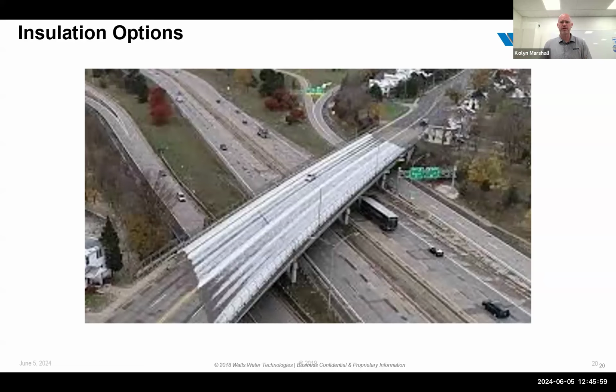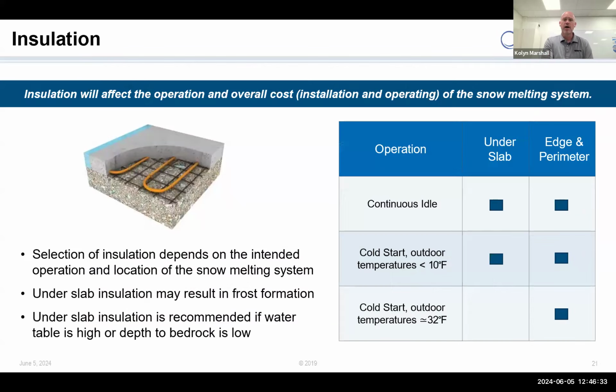When you decouple the snowmelt area from the earth, those fall days, those shoulder days where you actually end up with frost and ice buildup, like on your car windshield, will actually form on your snowmelt area. It's not a precipitation event. It's not going to trigger the sensor into turning the system on, but you can actually have ice buildup because of frosting on the surface because it's decoupled and doesn't have that residual thermal mass effect. So some things to take into consideration there.